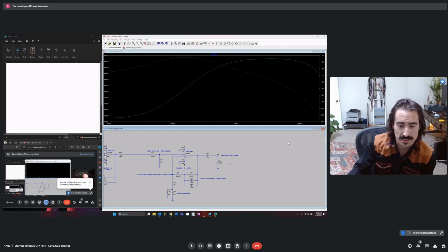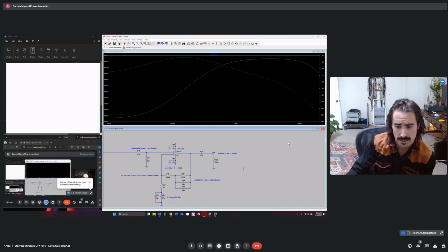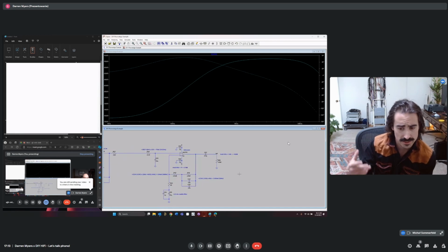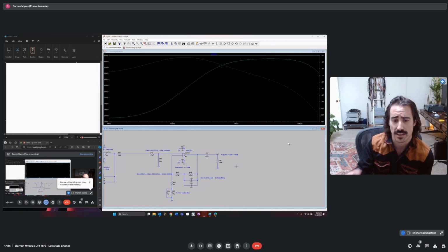But for somebody who wants to build this, and you're starting out and you don't have too much experience with building complex projects, I would just capacitor couple it and just not worry about the DC element, because it can certainly get a little bit more complicated, a little bit more involved when you're designing the servo circuit. So that's the reason why I left out the servo.